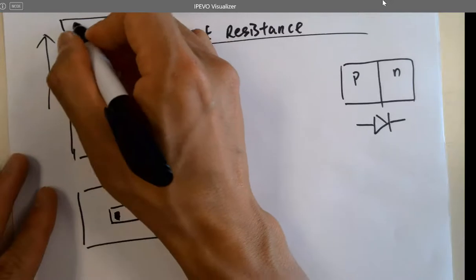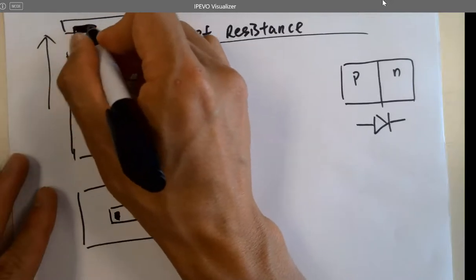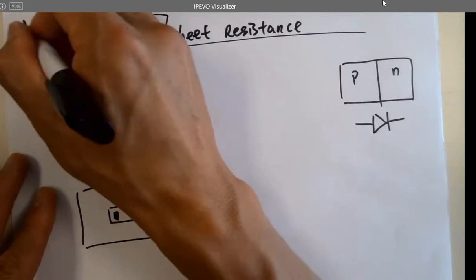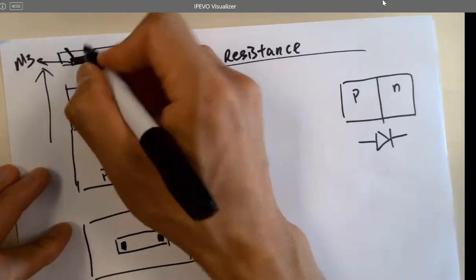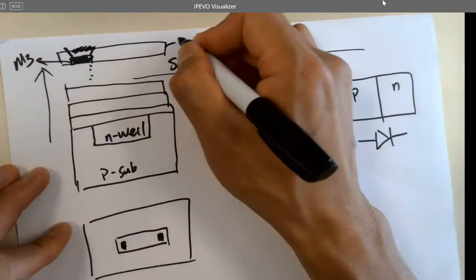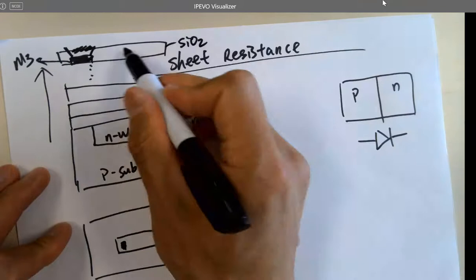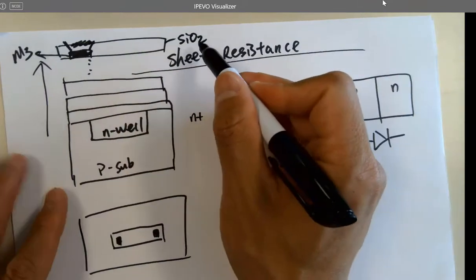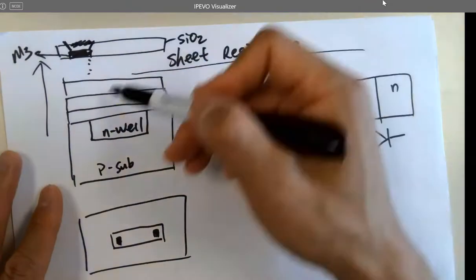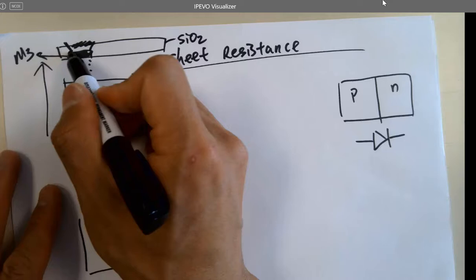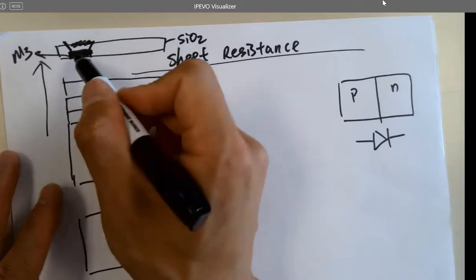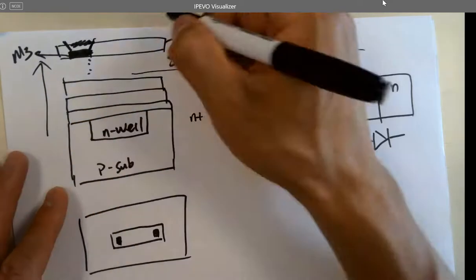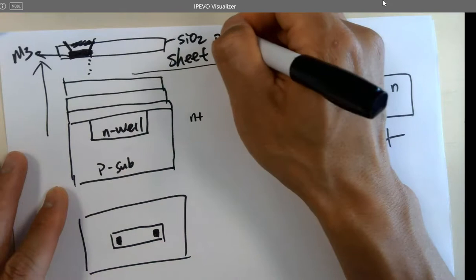But on the very top layer, here's the very top metal layer. It's called metal 3, and you can open it up in your design, so it's not covered by silicon dioxide. All the other materials are silicon dioxide, which is the insulator, to separate all the different layers. If this layer is a metal 3, you have a piece of wire from metal 3 in Electric VLSI, you can lay it out, and you can open it up. This is also called the passivation layer.